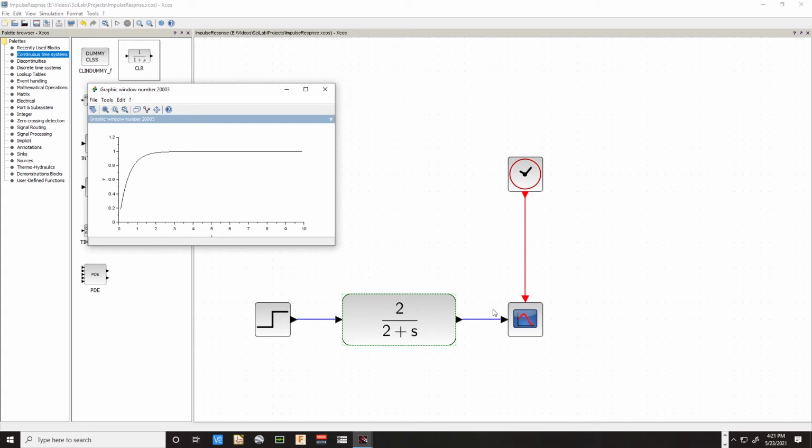And what we have to do is figure out what that function is for the particular system we're doing. Now, sometimes if you're controlling certain things, if it's a product you're controlling, the engineers that made that product may have a transfer function. It could be in the technical specs, and it'll be in this kind of form. Or they might give it to you in some other form, which you have to then derive. They might give it to you in the time domain, and you have to do Laplace on it. You can also collect data. This is sort of like taking a pendulum and whacking it and watching it swing, collect the data on it, and then work out the transfer function.